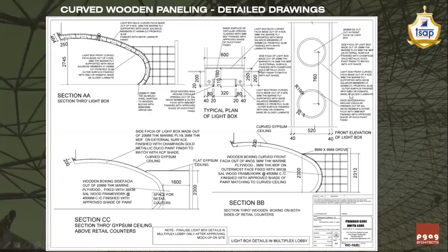Now, why is it important to write all the specification? If you miss writing any of the specification, the contractor is going to get advantage. He is going to take advantage of that particular loophole, I would say, because he will not use the laminate which is not of Homopal make, or which is not of the make which we desire.